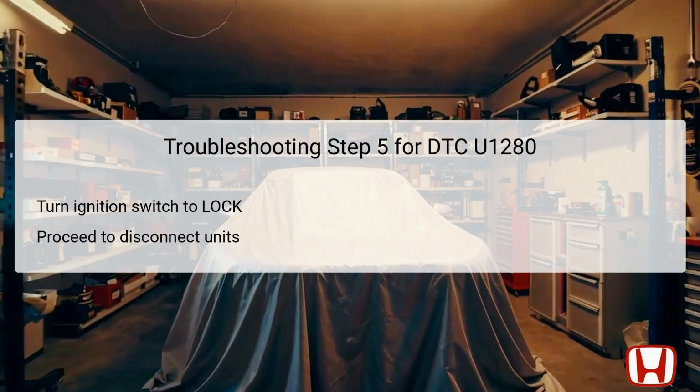Disconnecting the units one at a time allows for a methodical approach to isolating the problematic area, ensuring that you're not overlooking any control units that may be contributing to the issue. It's vital to ensure that power is properly disengaged when handling electrical components to avoid additional faults or injuries. Following this procedure will aid in identifying which specific control unit might be causing the bus communication error.